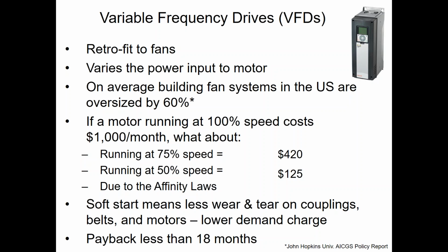We do have some compressors that we run with VFD inverters, and we do overspeed those. So like the compressor I have at my own house has an inverter on it, and it will overspeed beyond 60 hertz. But it was designed for that. So just doing that randomly on a job might be a problem.